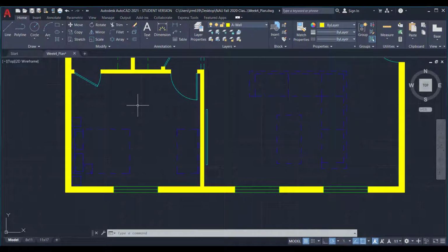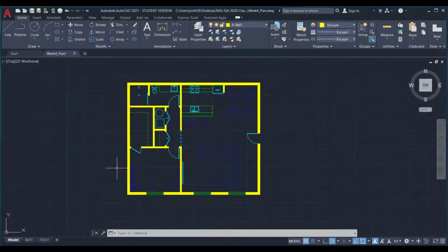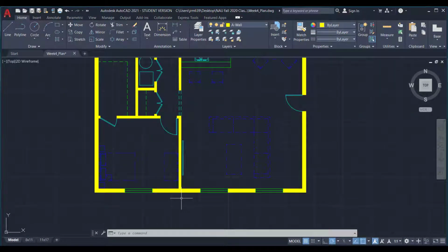You should do hatch, enter, when you're doing a ceiling. Now the walls, it doesn't really matter too much, but the ceiling plan it will. And there might be times where it is important for you to hatch separately. So just understand that when you type the word hatch and then you click inside, you can click in multiple spaces, or you can click one at a time. This space, this space, this space.